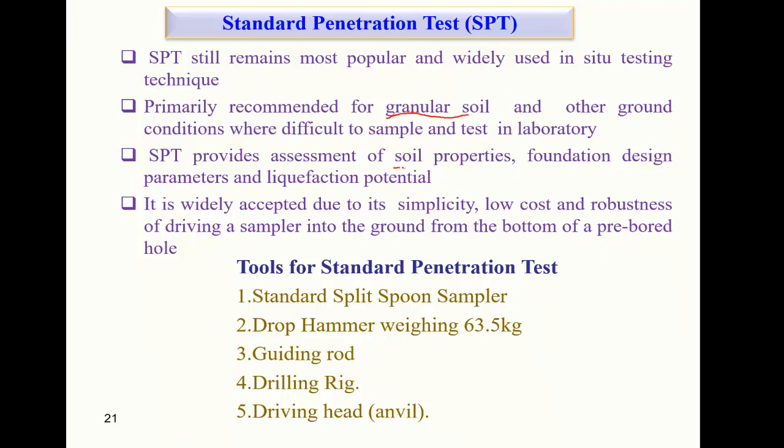SPT provides an assessment of soil properties and foundation design parameters. To design a foundation in RCC, maybe a footing, you use many soil parameters, and you can find these parameters from the SPT test.